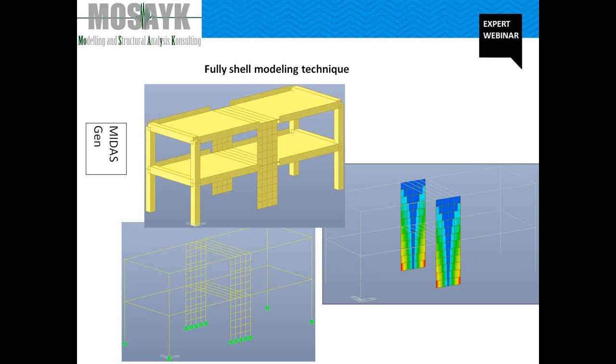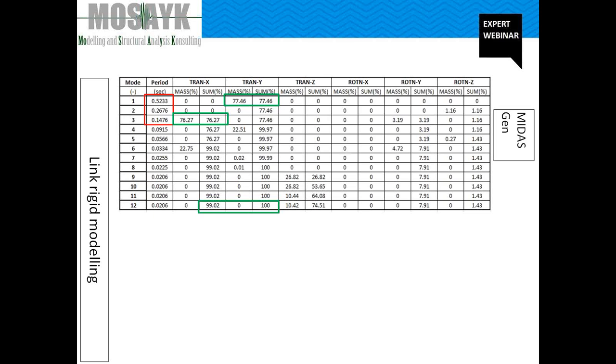If we use thick element like Timoshenko theory, we follow the shear strain on the panel itself. Using the thin shell element, we can obtain the real distribution of the stresses along the wall, for example, that can be used for distribution of the reinforcement, and the real geometry representation of the full building.